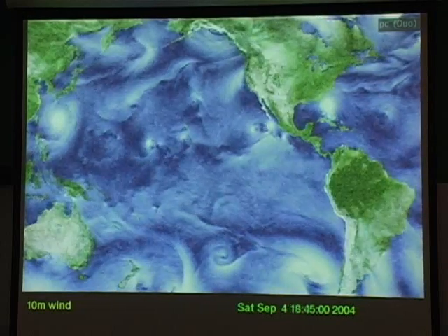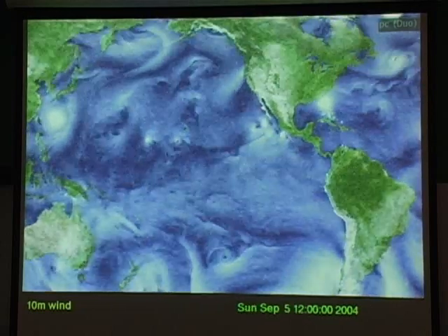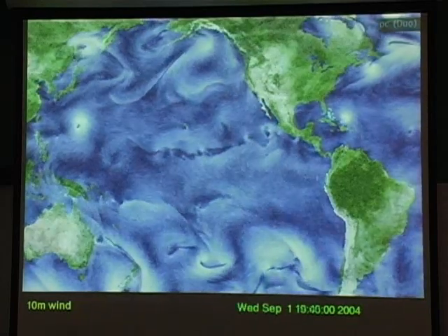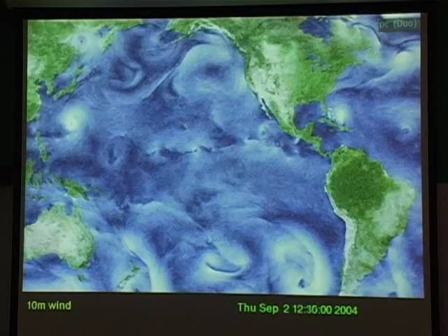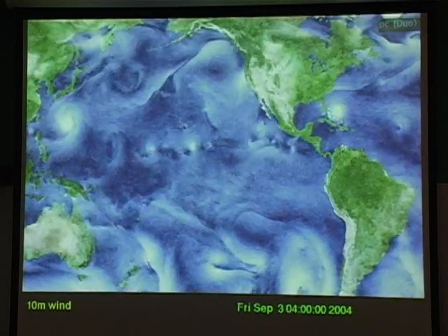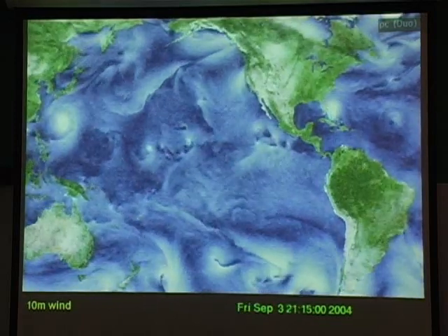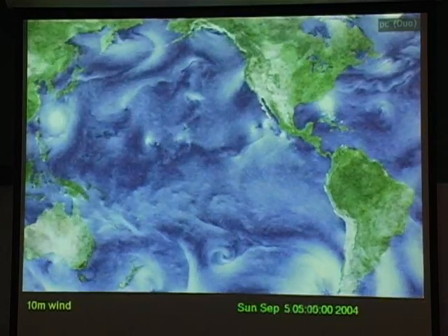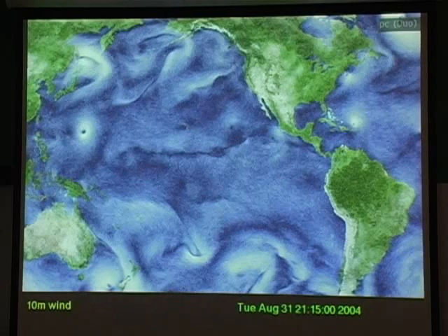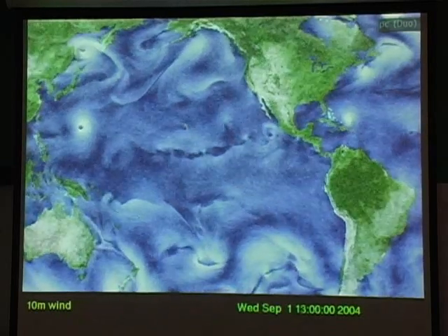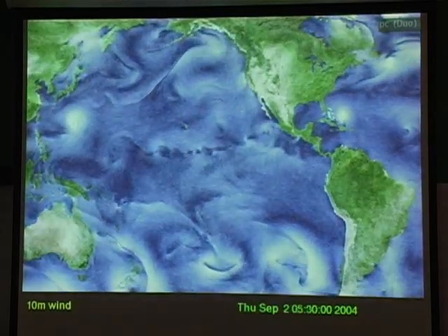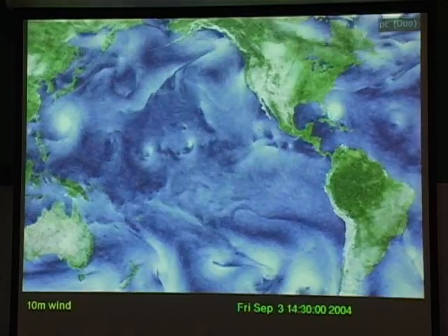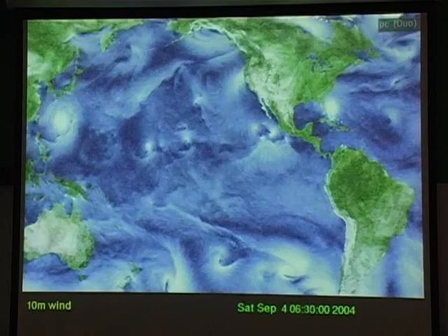This is using a technique called LIC, or line integral convolution, which basically combs a noise field with the flow field. The high frequency modulations you're seeing here, the moving streaks, are showing the direction of the flow. The low frequency modulation, the bright white areas and the not so white areas, is proportional to velocity magnitude. So you can see that the big cyclonic motions are quite a bit faster, and there are some doldrums down the equator and so forth.